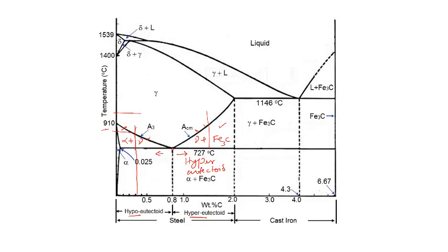If we call that T1, alpha is going to nucleate, but this is not the eutectoid alpha, isn't it, because the eutectoid reaction has not yet started. So that means this is the pre of eutectoid. In our metallurgical term we call it pro. So it is the pro eutectoid alpha, isn't it.